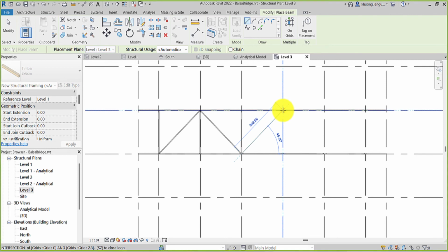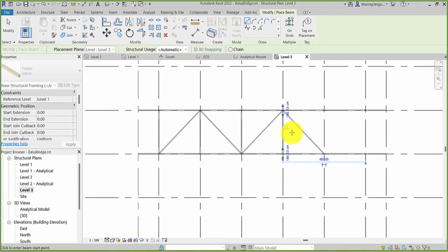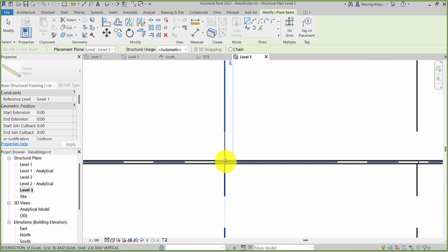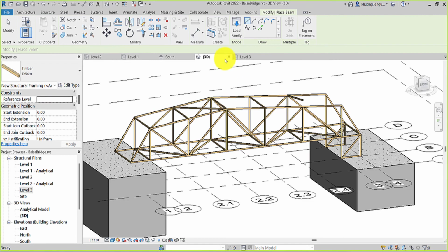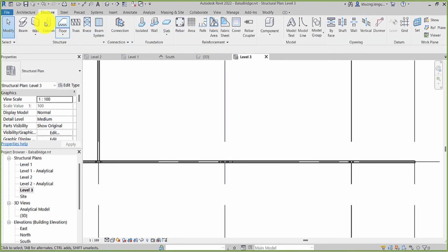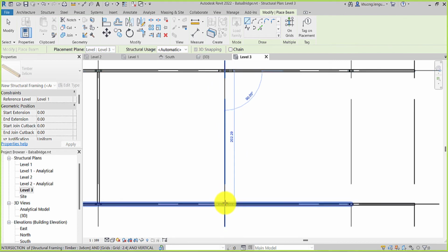In fact, pay attention when selecting the point. The element containing the selected point will appear, and it is useful to choose the right one. And I will give you a case that does not work. So it's not working now because we didn't choose the element. The element containing the point does not appear. It appears, that's good. The same for this. Okay.